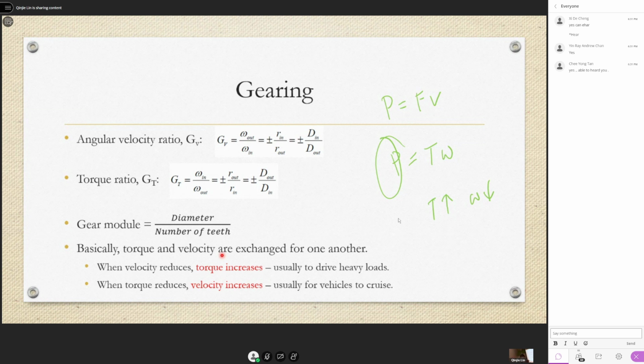So for the second gear, the driven gear, the wheel, to rotate faster and faster, what must you do? You must change the gear ratio, so that this can still rotate below 5,000 but the wheels can rotate faster and faster. You lower the gear ratio so that it is possible. If not, the engine cannot take it.